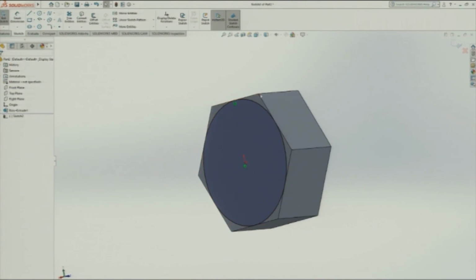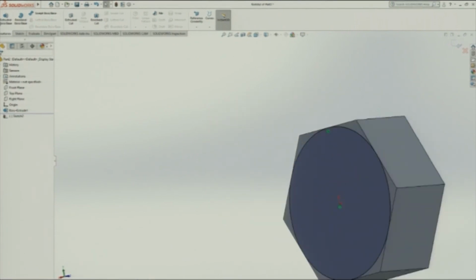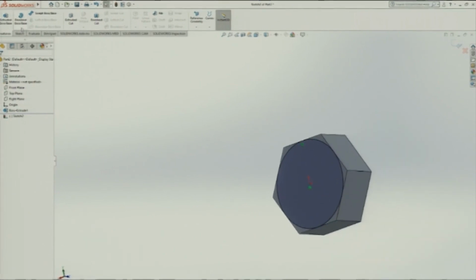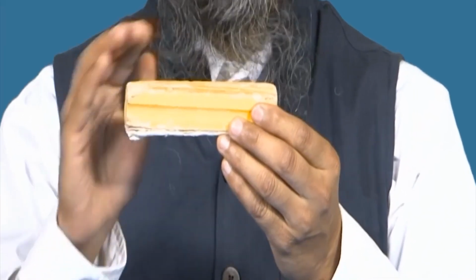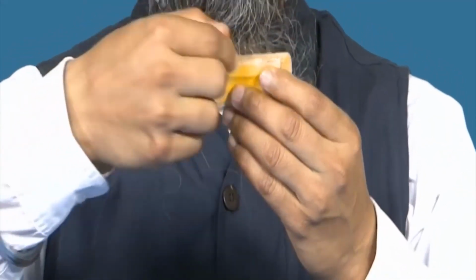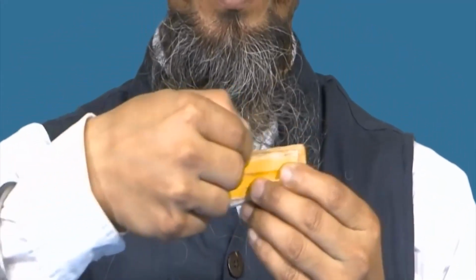Now, because the corners of the head are to be smoothed, I would say fillet wouldn't apply well here, it is actually drafted here. So, the draft command I didn't discuss. Draft command is something like making an edge slant. For instance, this is a completely rectangular body. If I need to draft it, I can put some angle here. So this body might become something like this. So this is the draft command.